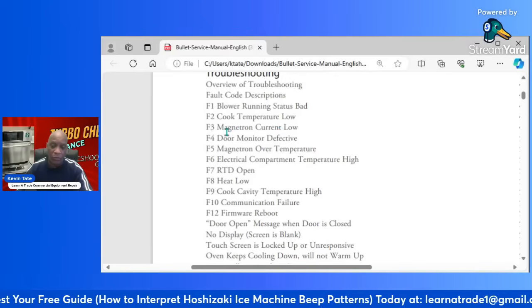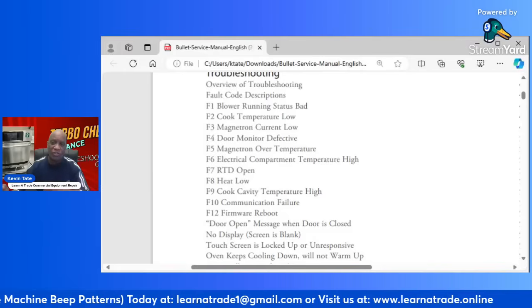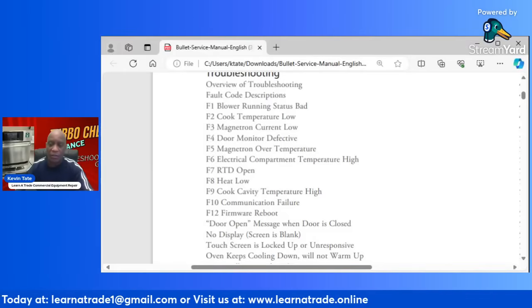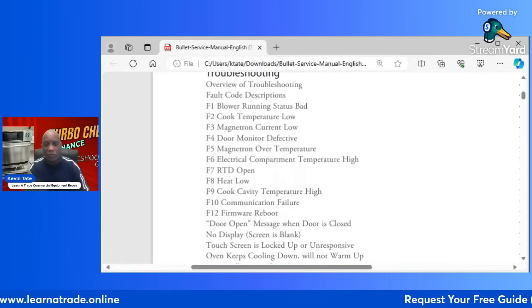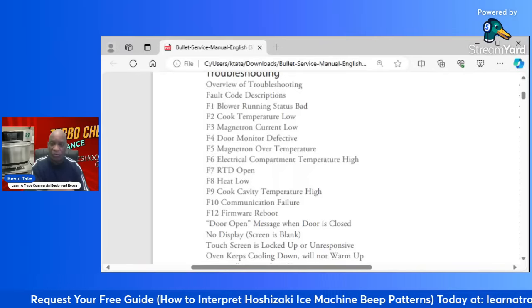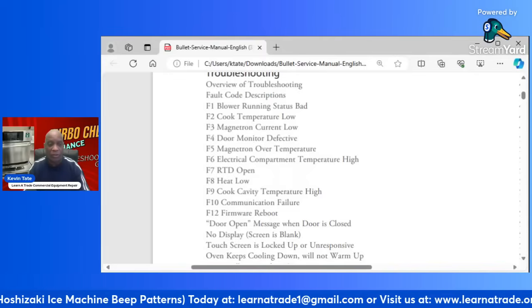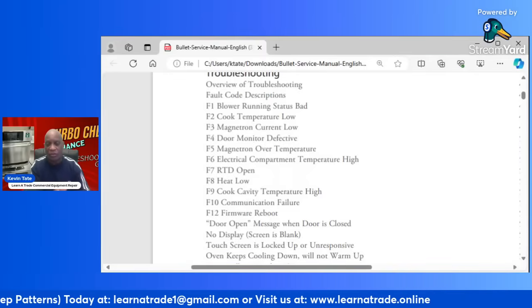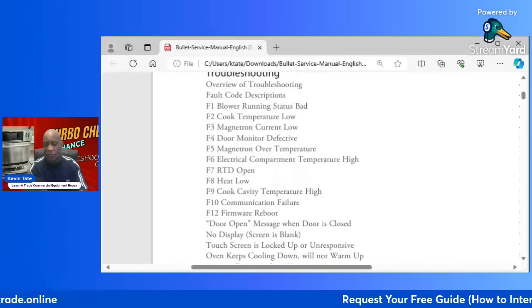And then also, you would take the right side panel off of the machine and check your K2 relay. If it's on these newer machines, it'll be up top. You'll see there'll be three relays just plugged into the top circuit board there. If they're the older models, the relays are all on your right side. So you just remove the right side panel, and then